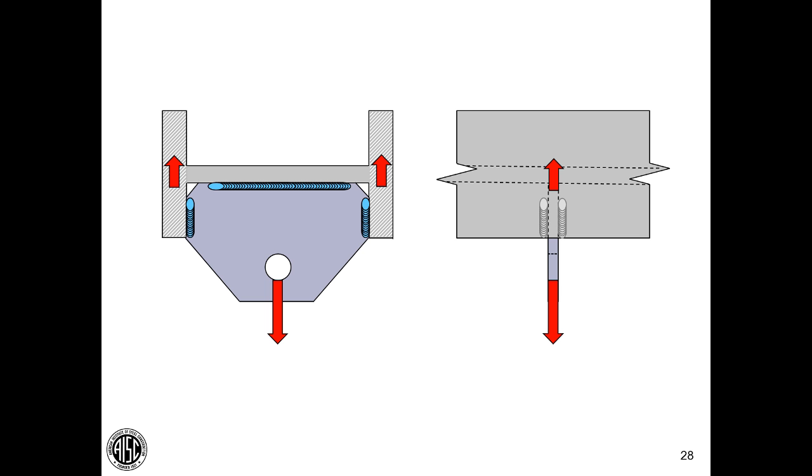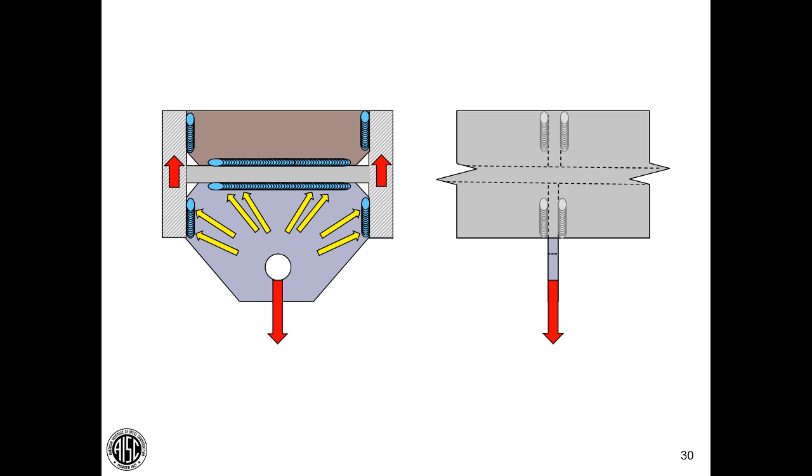That's the primary load path as shown by the yellow arrows. We could leave that weld off and size the two vertical welds to carry the loads alone. If you want to weld to the web, that's fine, but we should look at the load path when we're sizing the welds involved. If we add a stiffener on the back side of that beam, now we are creating a path that engages all the welds and allows that load to be transferred into the member that lies parallel.